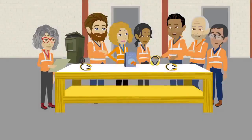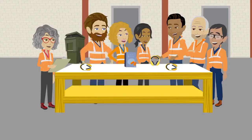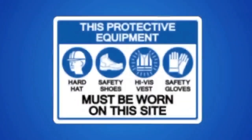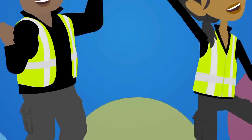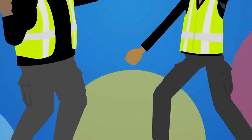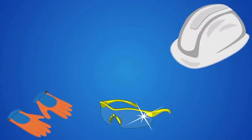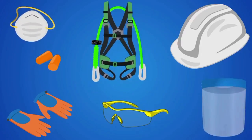As a team member, you are encouraged to participate in the risk assessment process and the development of safe work procedures by raising matters at your toolbox meetings and discussing them with your team. You must abide by all site and workshop signage and wear any mandatory and task-specific PPE. The minimum PPE is generally a high-visibility vest, long pants, and steel-capped footwear. Task-specific PPE may include gloves, hard hats, safety glasses, hearing protection, fall protection devices, face shields, and dust masks.